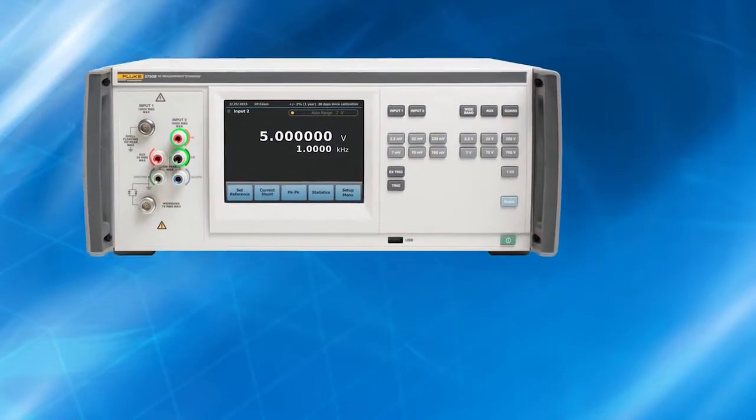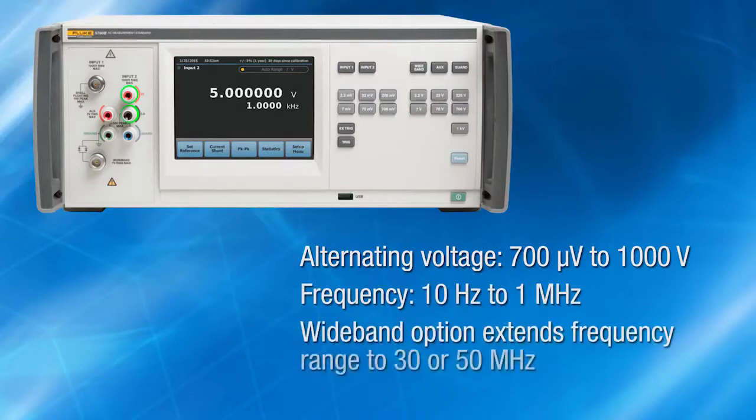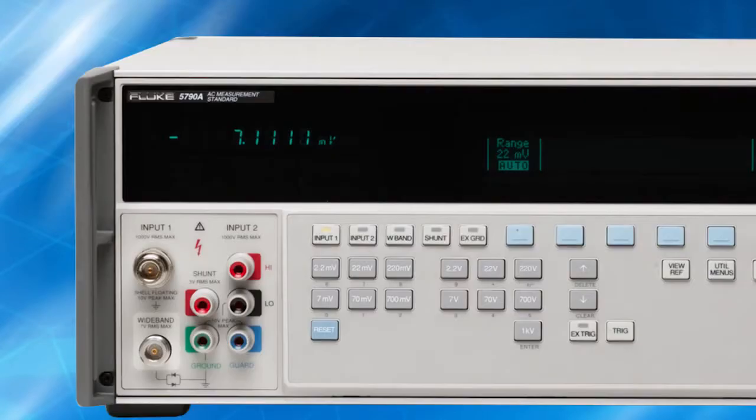The 5790B covers an alternating voltage range of 700 microvolts to 1000 volts and a frequency range of 10 Hz to 1 MHz. A wideband voltage option extends the frequency range to 30 or 50 MHz to meet the calibration requirements of Fluke Calibration 5700A, 5720A, and 5100 series wideband options.